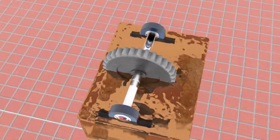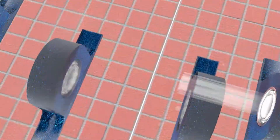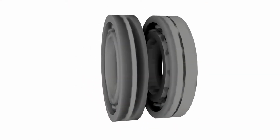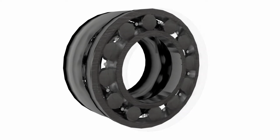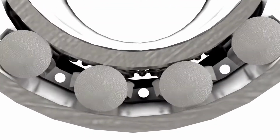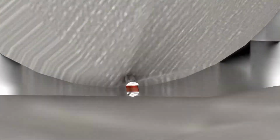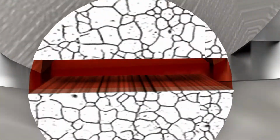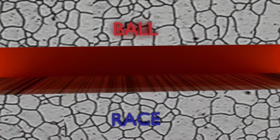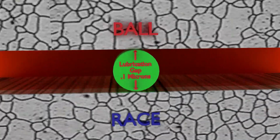John's problem stemmed from the fact that rotating equipment contained components such as gears and bearings, which require clean oil to remove friction between their sliding surfaces. What John didn't know was when magnified over 1,000 times, the lubrication gap between the sliding surface of the ball and the race of his bearing could be as small as 0.1 microns.